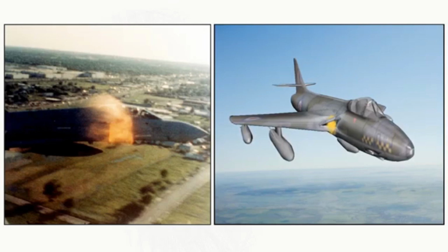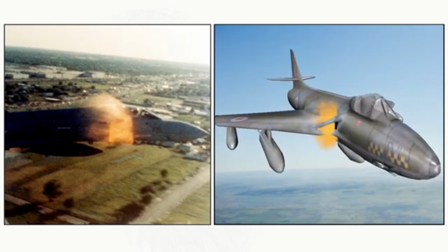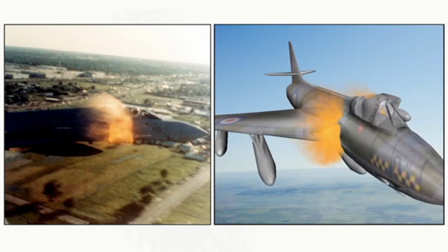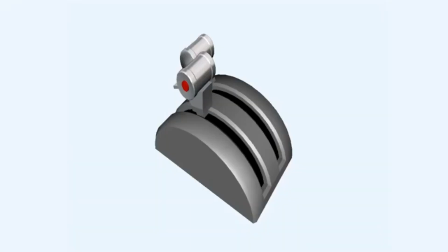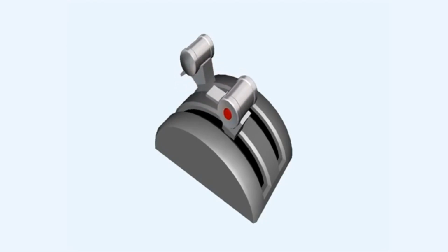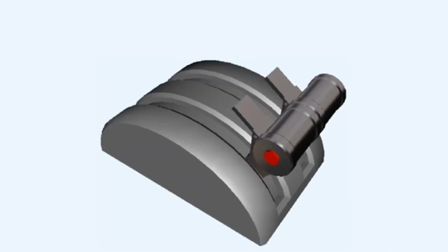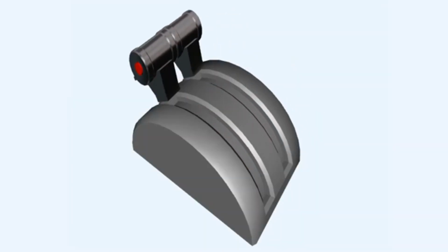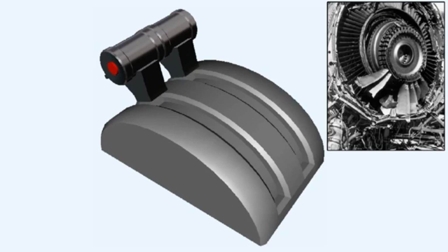In severe cases, a surge could cause an instantaneous reversal of the airflow through the engine, with air being expelled through the engine intake with a loud bang. If surge does occur, the throttle of the affected engine must be closed slowly, and the cause investigated. Surge is most commonly caused by either fuel system malfunction or engine control mishandling. In extreme cases, a surge can inflict such large bending stresses on the compressor rotor blades that they contact the stator blades, with potentially catastrophic results.